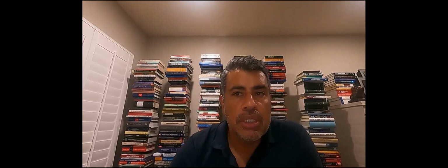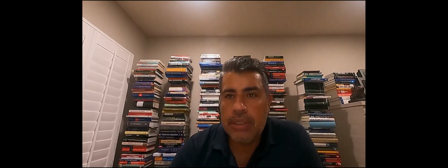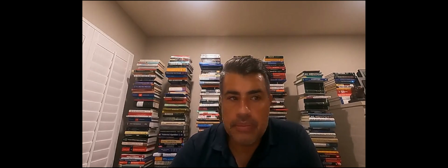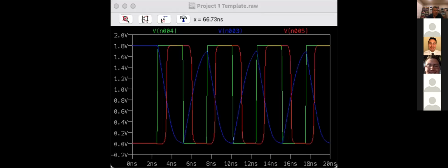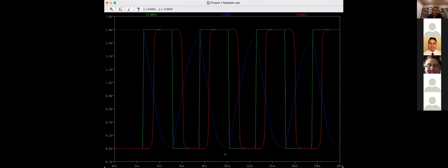So let me simulate again. Now I got 1.5 picofarads, and I would say this is definitely not working. These rise fall times are just not fast enough to deal with this period.